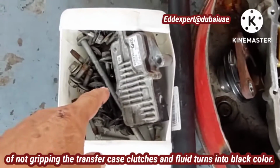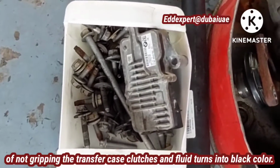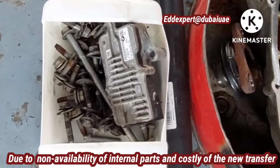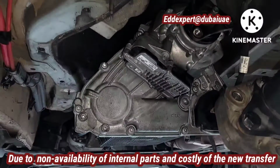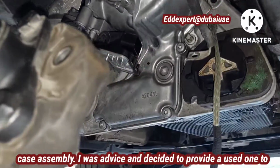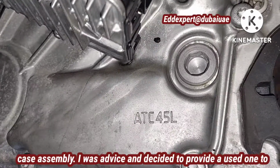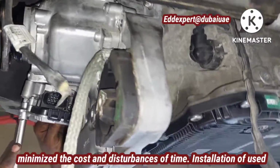I replaced the actuator because it's mentioned also the four-wheel drive always. So I put a new one, but I received the same code. Due to non-availability of internal parts and the cost of the new transfer case assembly, I was advised and decided to provide a used one to minimize the cost and disturbances of time.